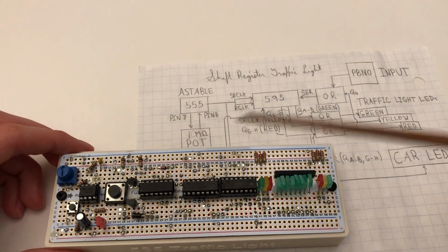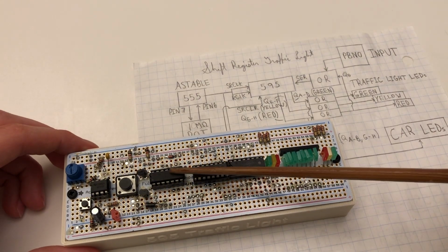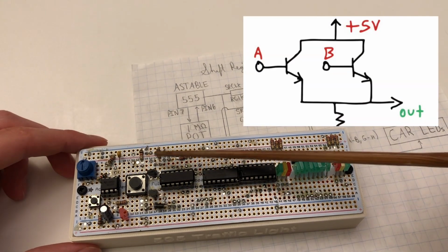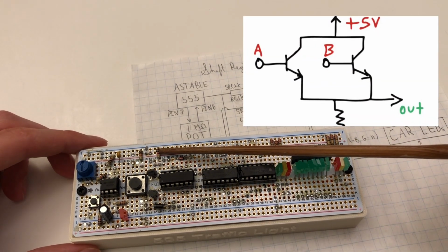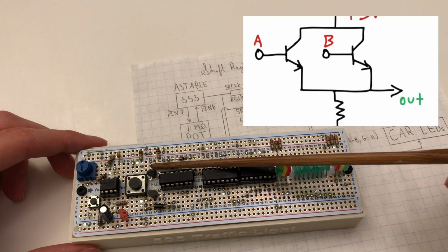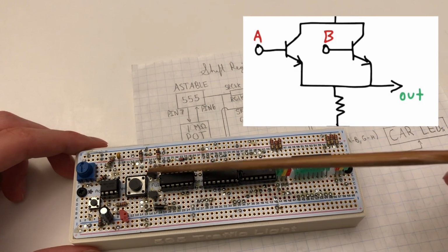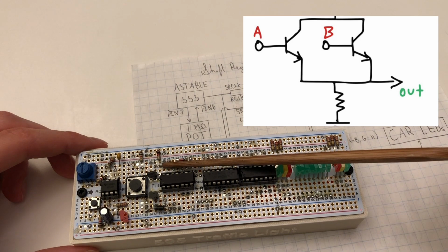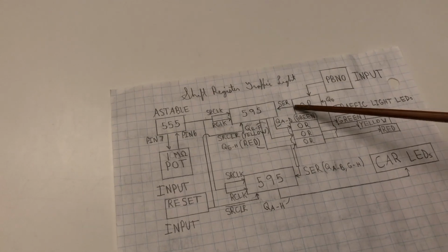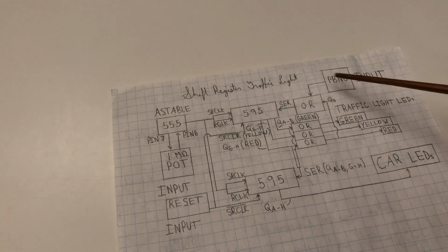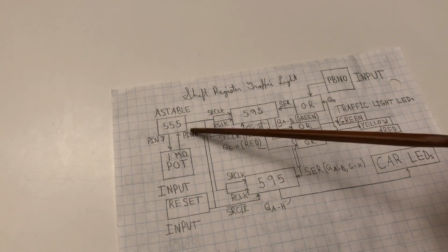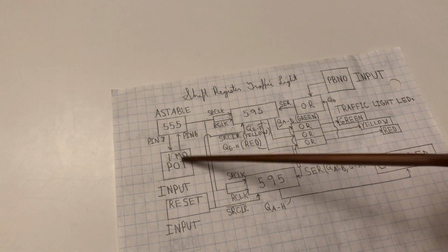This top OR gate here is actually made of transistors because I didn't have enough room to put another OR chip onto the full-size perma-proto. The collectors are both connected to power, and the emitters are both connected to ground. So since these are NPN transistors, whenever a high is presented on the base pin of either one, it'll connect it to 2 pins and therefore outputting a high and serving as an OR gate. So when you press the button, a high is outputted on the data pin, and ideally you'll press it for 1 clock cycle.